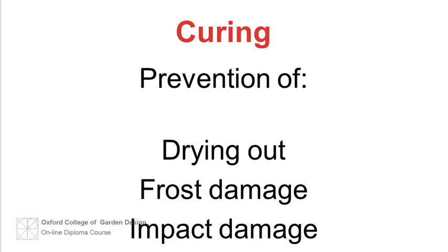Concrete should not be poured at or below 2 degrees centigrade, nor should it be poured onto frozen ground or against frozen formwork. The mix should be at 5 degrees centigrade minimum. The temperature can be raised in winter by using hot water in the site mixed concrete or by specifying the required temperature for the ready mix.